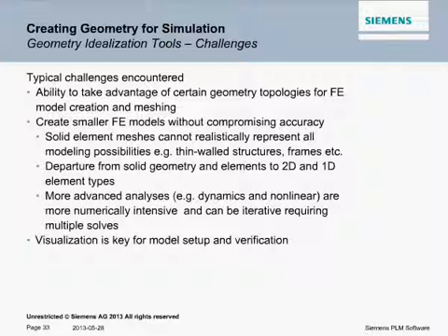So there may be cases where we need to depart from the solid geometry and solid elements and start to use two-dimensional or even one-dimensional element types. I mentioned just now more advanced types of analysis like dynamics and nonlinear are more numerically intensive, and actually, they can be iterative as well. So it's multiple solves, not just a single solve.